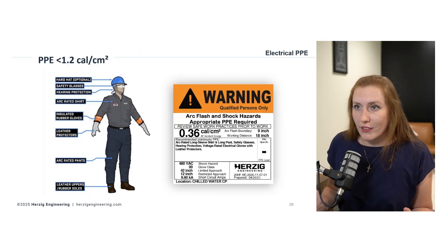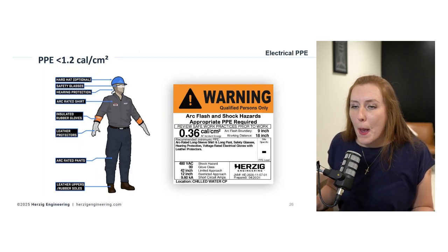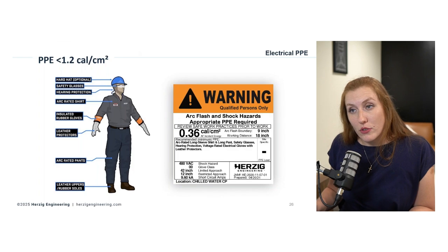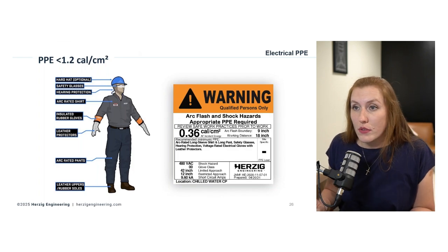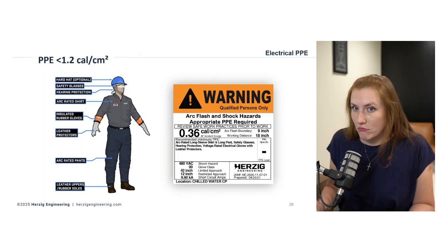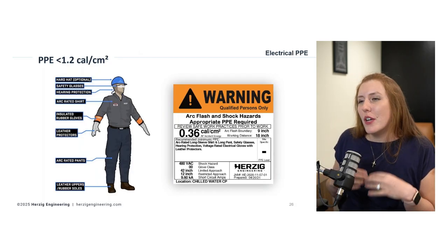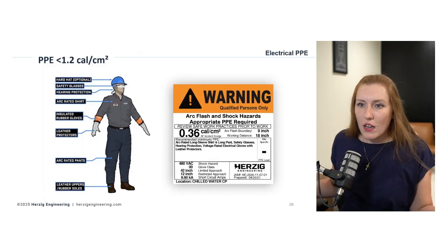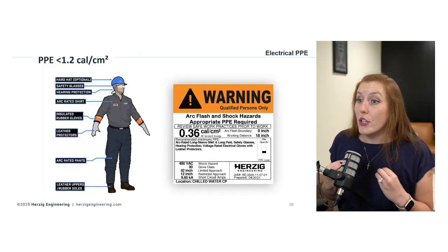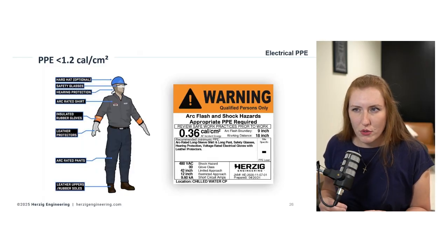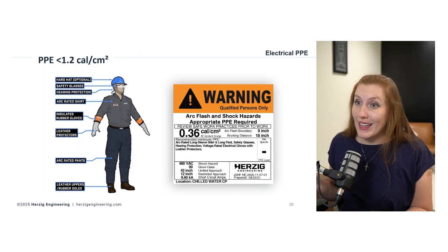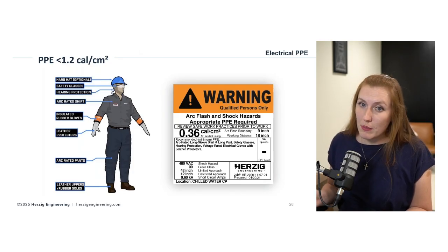Arguably, there's not an arc flash hazard, quote unquote, there, right? But there's still shock hazard potential anytime it's exposed and energized. So that's not no PPE, it's just maybe not arc flash PPE. So I would say go ahead and calculate it all out and put the labels on just to be certain. No guesswork, no assumptions. They know, is it a hazardous level that requires PPE or not?